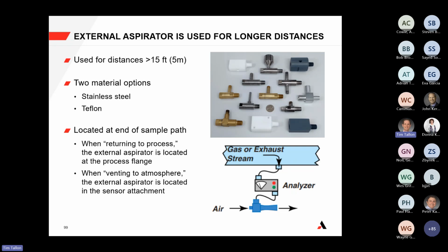Well, first of all, we use 3/8 inch tubing. A lot of our installations are short coupled. We haven't had much of an issue of plugging occurring by either particulate or by the sample reaching a dew point and dropping out. But if it does, that's the one reason why we have the spare line.